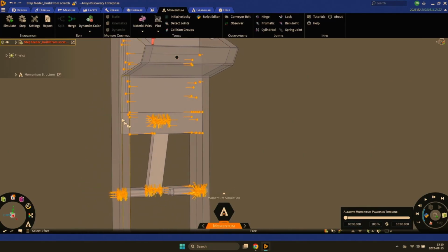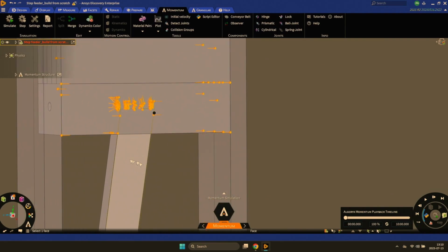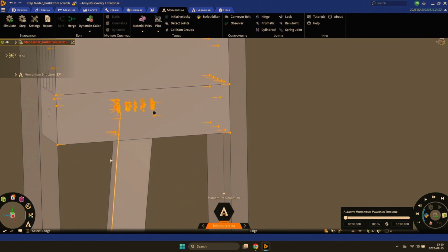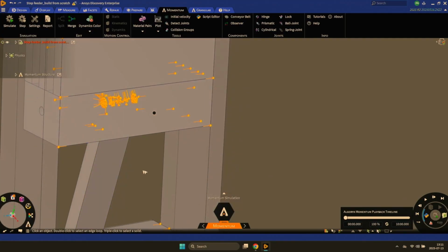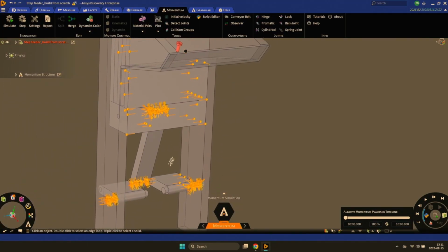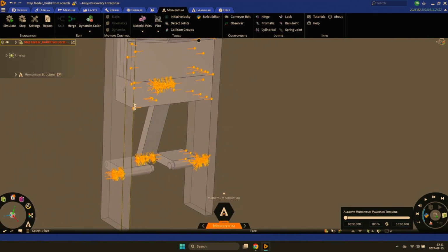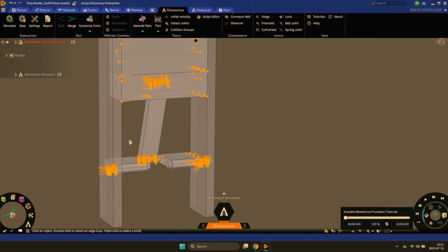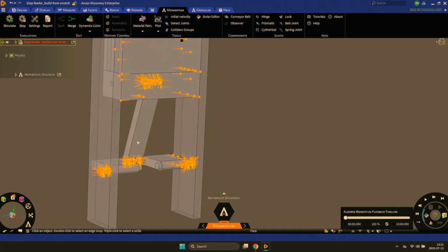So there's no built-in clearance and play into the assembly. So if you were to build this machine in real life, it would just jam, right? Because there's no play in the model, and the same thing happens in the simulation. So here we have a choice.